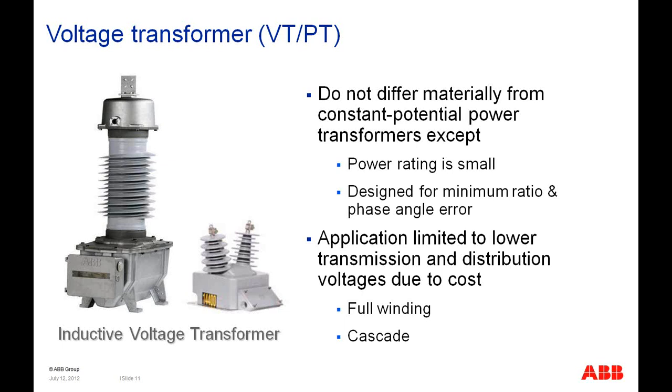The application of voltage transformers, though, is limited to values typically less than 69 or possibly 138 kV. Typically at 69 kV and below, you tend to use a magnetic voltage transformer, and above 69 kV, because of economics, we tend to use a coupled capacitor voltage transformer instead.